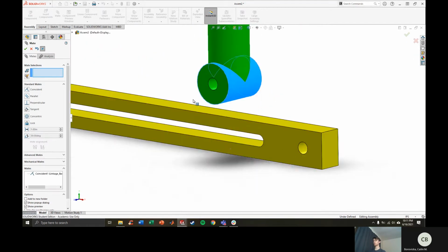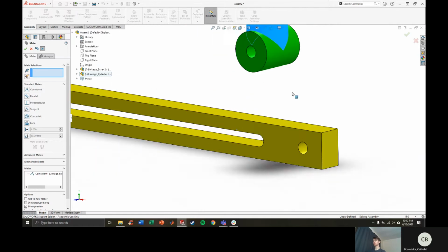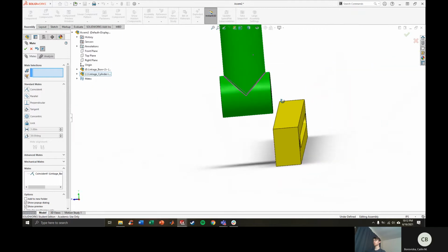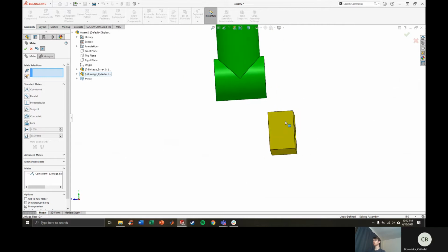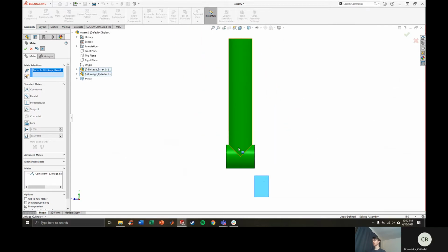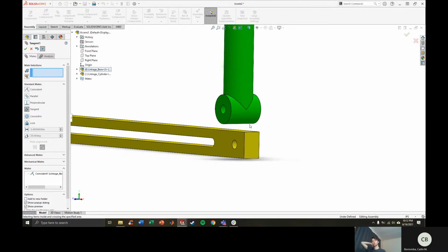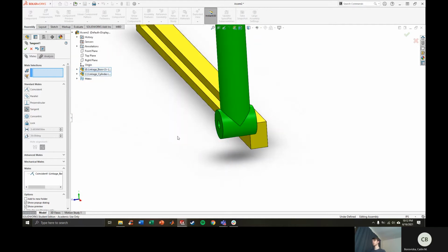Now, this part is still not constrained. If I were to open this up, you can still see it as a negative because it can move around all like this. But if you look at it from actual side on, it can't actually move in this direction. So that is one constraint. Usually things will have 3 to 6 degrees of freedom depending on what they are, so you have to constrain all of them. Right now we have constrained 1 degree of freedom.